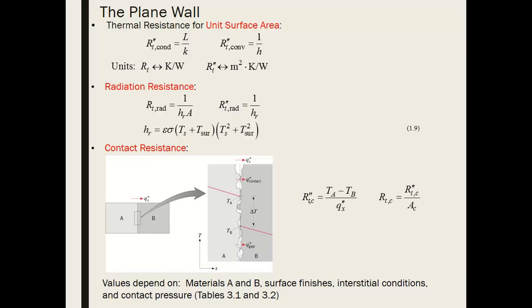So that same basic definition applies. We use this algebra where we factored the Stefan-Boltzmann law to get out a raw temperature difference from it. And we've made an algebraic form of this radiative heat transfer coefficient, so it looks a lot like convection. And because using this form makes radiation look like convection, the thermal resistance for a unit surface area looks similar as well.